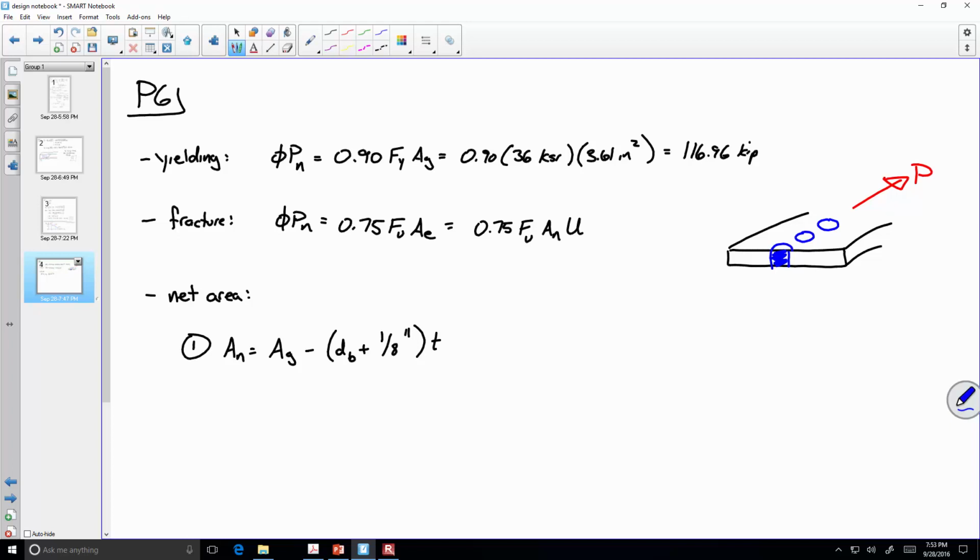Would the FE calculation be like 1/16? Well, if you look at that, that's what I was mentioning earlier. If you look at the formula, it says that the net area for parallel holes is the sum of the diameter of the hole plus a 1/16. But then look at the very top, the diameter of a hole is the diameter of a bolt plus a 1/16. So I think that's misleading, personally. I think they should just collapse it, but that's me.